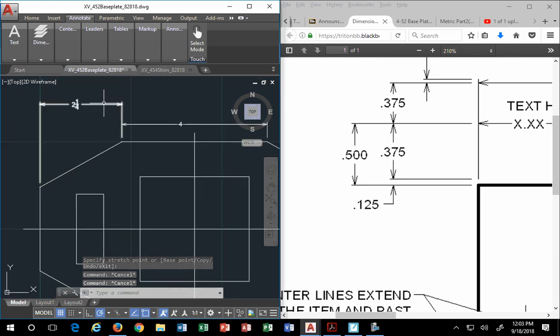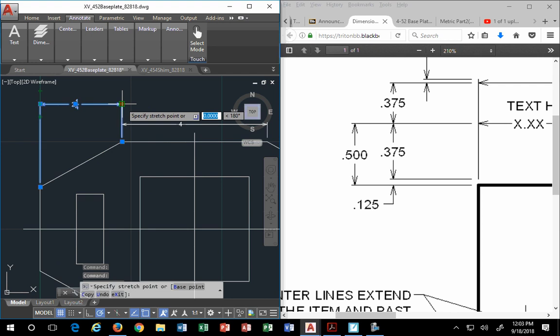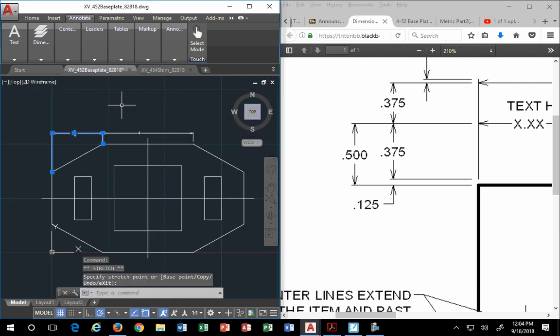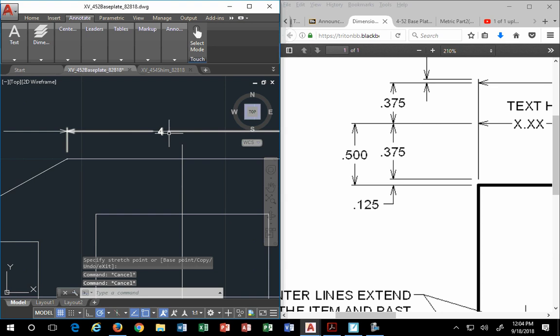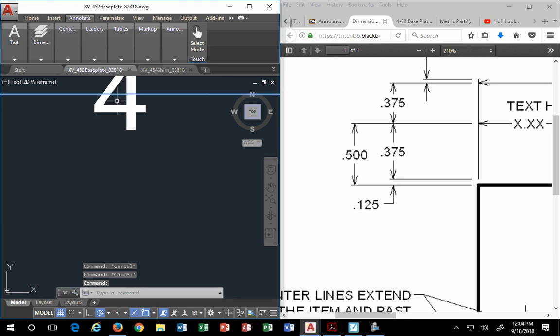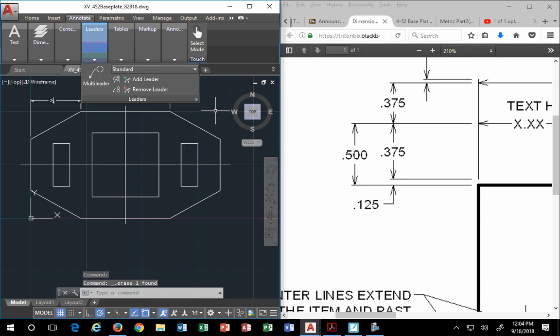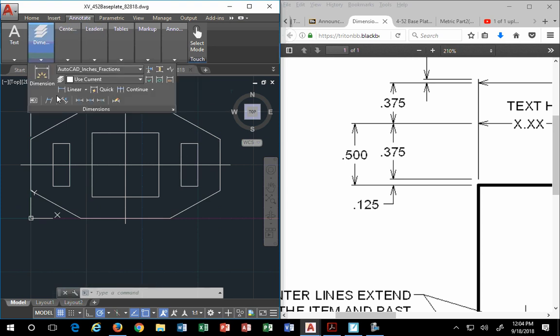And then this dimension can also be equally dragged down by its grips, so that lines up with that. Now those things are in the right spot. You have a little line back there, though, that you have to delete. Now, if I want to add a dimension above this, now I can go ahead and use something called linear. Not linear, sorry. Over here under baseline.